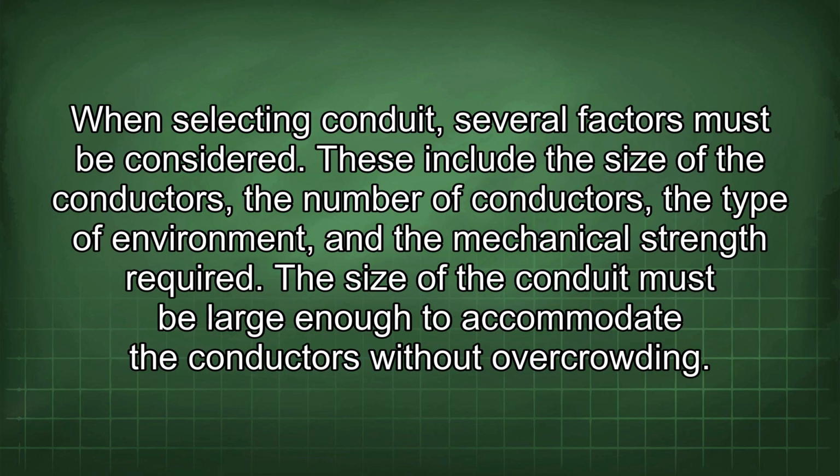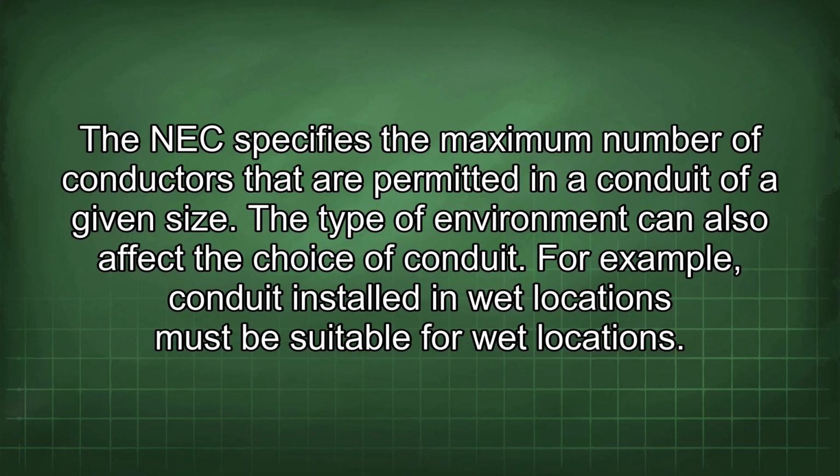When selecting conduit, several factors must be considered. These include the size of the conductors, the number of conductors, the type of environment, and the mechanical strength required. The size of the conduit must be large enough to accommodate the conductors without overcrowding. The NEC specifies the maximum number of conductors that are permitted in a conduit of a given size.